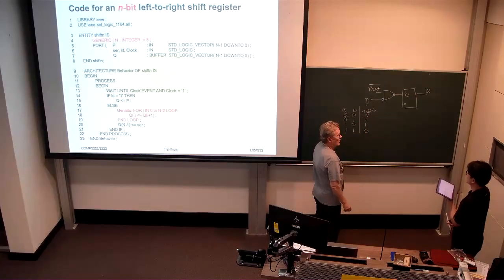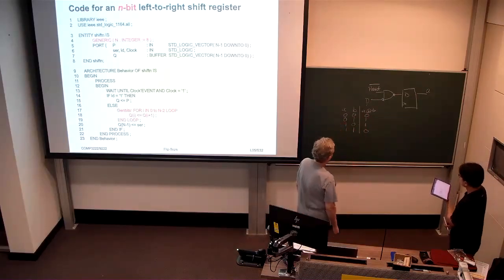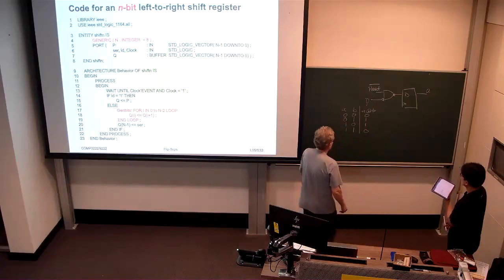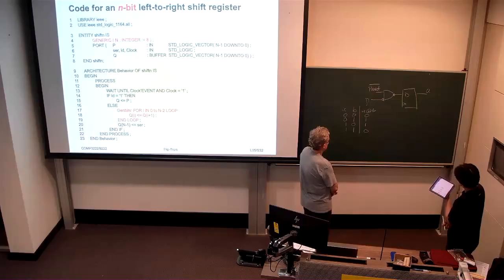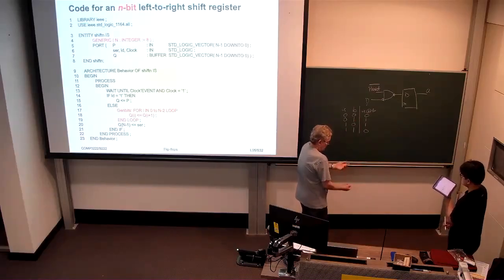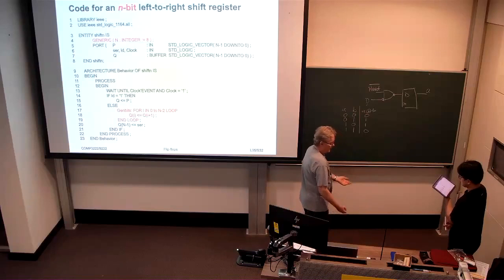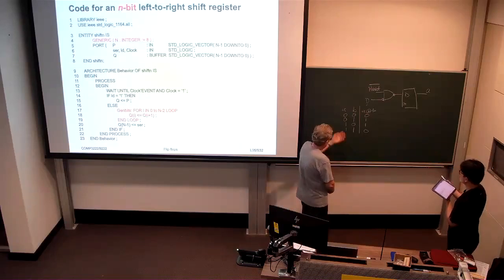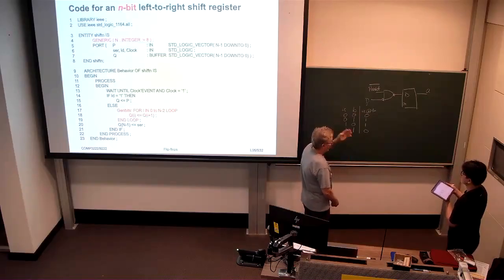XOR. Yes. And what does it tell you? If they're the same or not. No, it doesn't. When is it 1? It's 1 when they're different. So what would tell you when they're the same? What would the output look like if the gate is meant to tell you that they're the same?